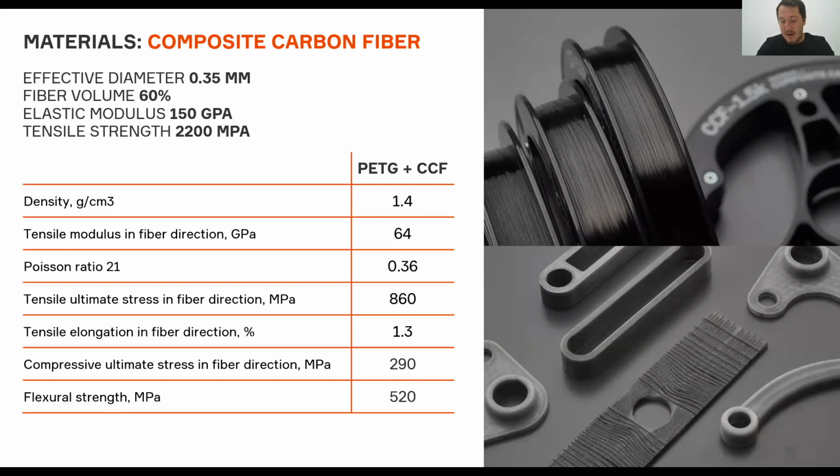Normally the fibers are highly permeable with such formulations. So we are able to achieve 0 to 0.5% porosity inside the CCF, and 60% and maybe even higher fiber volume fraction in the reinforcing fiber.